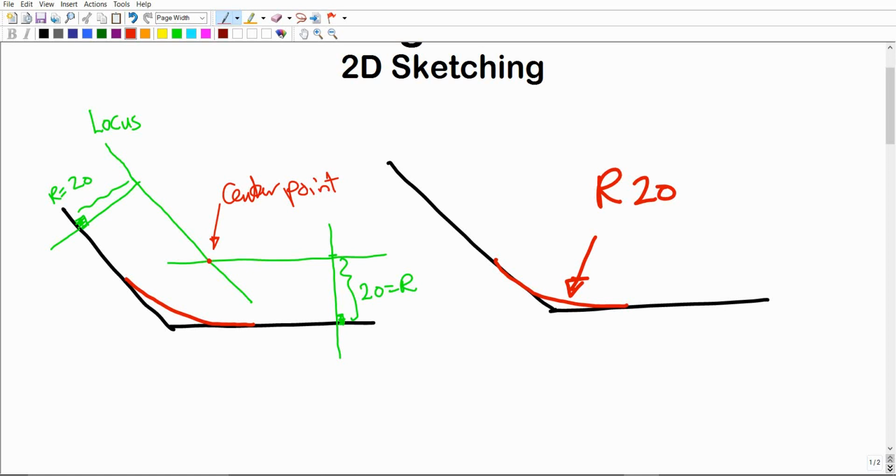So you'd have two options, as we discussed many times before. Either to draw, then you have to erase them using the eraser, you're gonna remove them. And in this case, you're already spending time or wasting time. Or the other option, just to draw this, use this line and make sure that they are very light, barely seen in the drawing sheet. So in this case, there is no need to erase them, and that is fine to leave them there. Make sense?